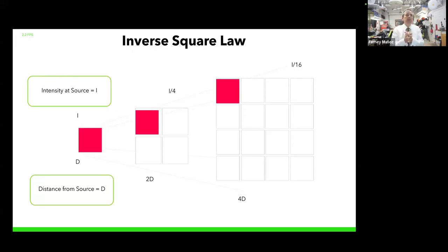The antenna, let's say, has a 13 dBi gain. Then what comes out of the antenna is what's called EIRP, effective isotropically radiated power. We'll do a graph and play with this in a little bit. Then that energy leaves the antenna. Those waves start going through, and every time you double the distance, those waves start attenuating at that rate. Double the distance, you end up with 1/4 of the power.